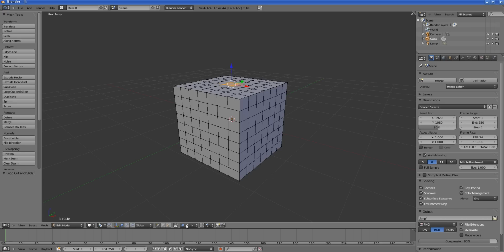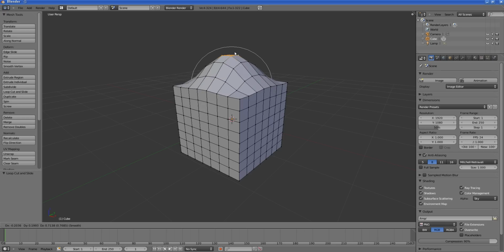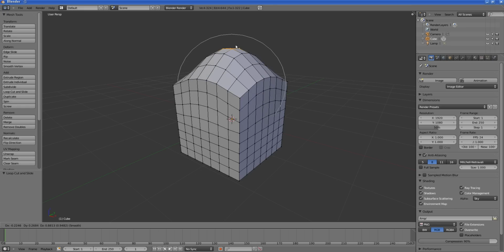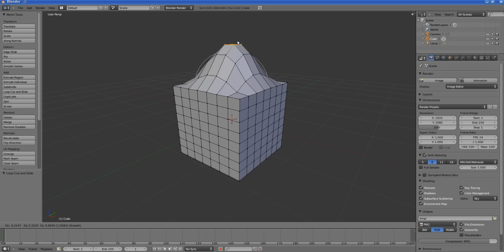Once you enable the proportional editing tool, as you move a set of vertices, the falloff is used to move the surrounding vertices. So let me press the G key and now there you go. You can scroll the mouse to control the area of influence of the falloff. And to change the falloff type, press shift and O. Okay, there you go. And again, if you keep your eye on the 3D view header, you'll see it'll give you which falloff mode is active as of now.